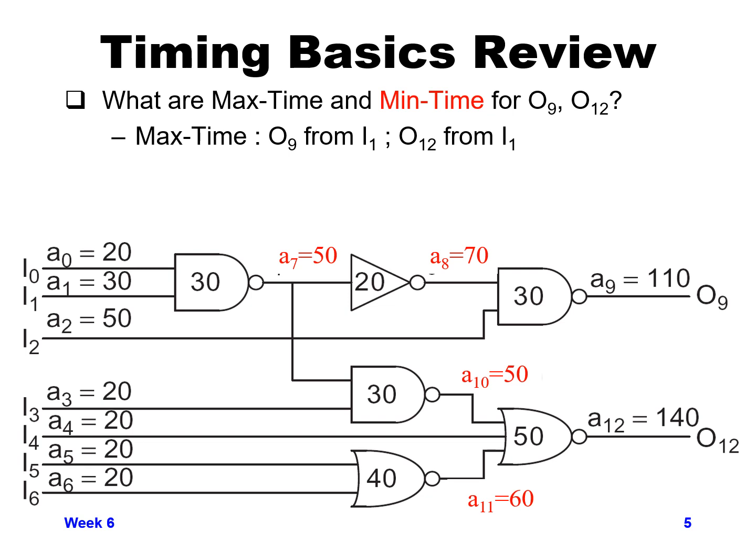Now let's go, in the same order we did last time, up to output O9. We have the NAND gate there. It has 2 inputs. Input A8 timing is 70. The other input, A2 timing, is 50. So the quickest of those two is 50. We add 30 to it, and A sub 9, quickest, is now 80 instead of 110.